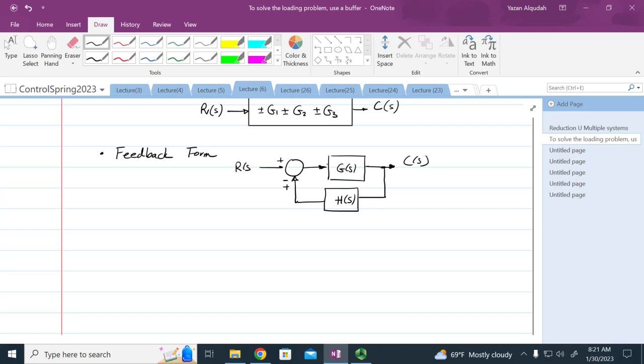What do I need? I need a sensor to measure the temperature. What is that sensor going to do? It's going to take the temperature and give me a voltage that corresponds to that temperature. What is this transfer function going to represent? The transfer function of that sensor. Does that make sense? So anytime I see H of S here, it tells me that the nature of this input is different than the nature of that output, and this sensor is translating this nature to this nature.